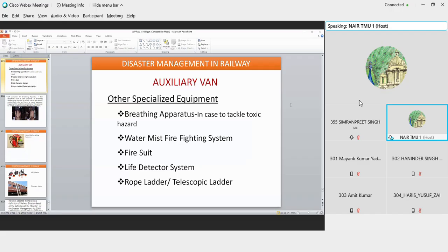The function of the auxiliary hook is that, assuming you have to pick up a smaller component, the main hook is doing a lifting process, which is a 140-ton hook, and you have lifted the wagon, but there is an axle which is available. An axle is weighing around 3 to 4 tons, or a wheel set is weighing around 10 tons. Rather than using the main hook, you would use the auxiliary hook, which has the capability to lift 25 tons. You'll basically use that auxiliary hook, and you will not use the main hook. But this brings to another question. You see what happens. The crane also has the main power pack, and it has a smaller auxiliary power.